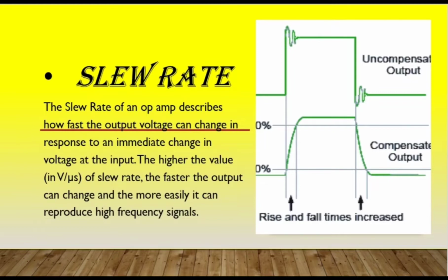It is changing at its fastest rate as the signal voltage crosses zero, and the rate of change falls momentarily to zero, no change, at both the positive and negative peaks of the wave. If the slew rate of the amplifier cannot keep up with the fastest rate of change of the signal, some distortion will be produced. So,